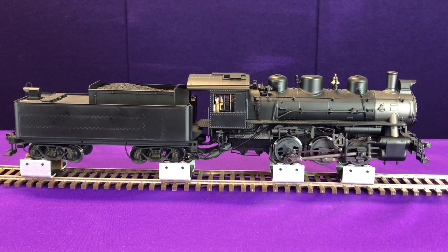Now, one of the other advantages is, let's say for example we want to run our locomotive a little faster. Well, there's a lot of times where the firemen may accidentally put too much water in the boiler, and they'll suck water into the dry pipe. It's called oversaturation. And so the engineer would have to blow that water out of the system. So at speed, we can still turn on the F4 and blow out that extra water.